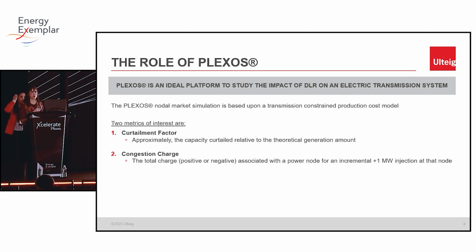So, as Nergui said, now I'm going to walk through how we actually utilized PLEXOS for this analysis of dynamic line ratings on a transmission system, followed by our results. PLEXOS is an ideal platform to study something like dynamic line ratings because of its vast uses. It can be used for nodal market simulations, probability or loss of load probability analysis, stochastics, capacity evaluation, and that list goes on and on. But for this specific research, we used the nodal market simulation capability of PLEXOS, which allowed us to do transmission-constrained production modeling of the transmission system.